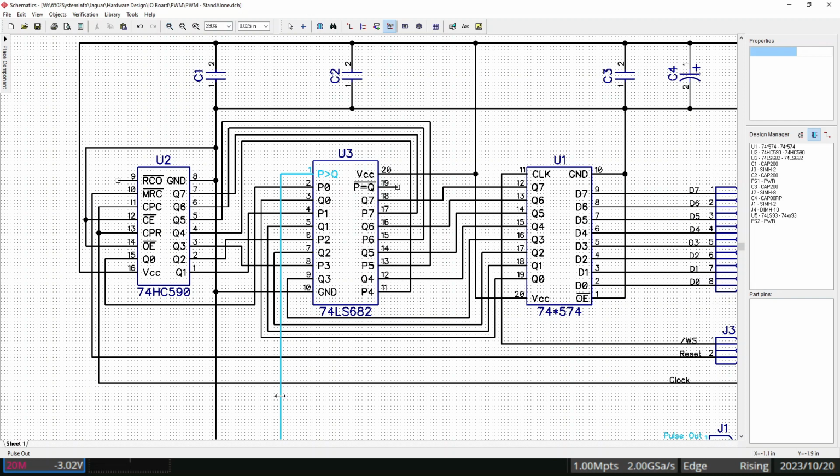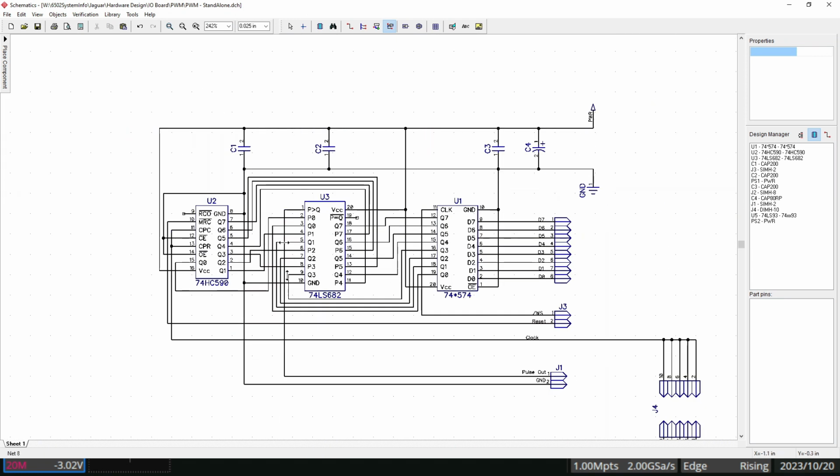And then for the next 127 cycles, it'll remain high. And of course, once it goes back to 0, P will be less than Q, so this will go back to 0 again. So you're literally counting along until P gets to be greater than Q, and then, bang, up it goes, and when this resets back to 0, it goes back down again.